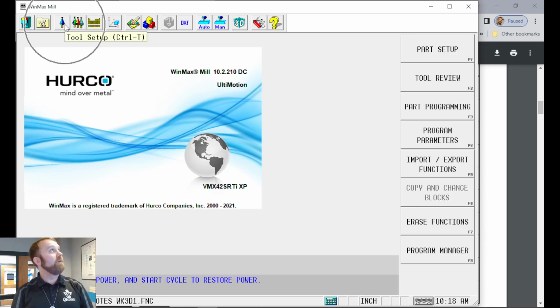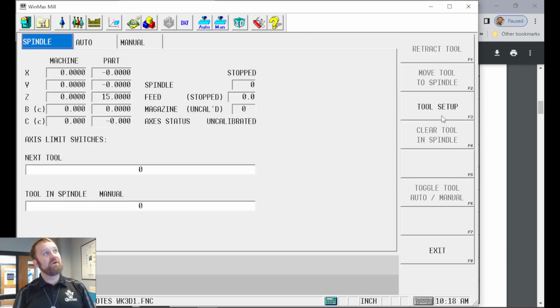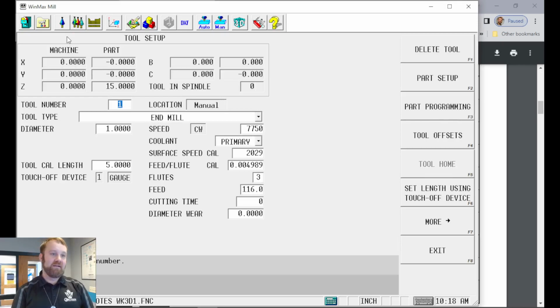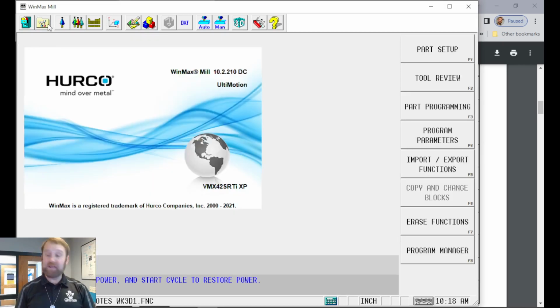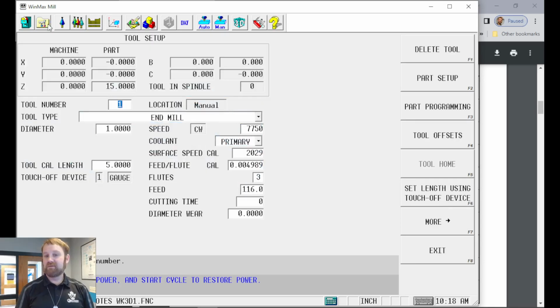Let's go to the tool library button. It's right here, tool setup. So you can go here. There's about 6 different ways you can go over here. You can hit the manual tab and go to tool management and go to tool setup. But I typically, when I want to get there, I usually do the hotkey. I hit Control T. Even out there, when I want to get to my tool setup, I just hit Control T on the keyboard. Okay, the machines out there all have keyboards that slide out, and I usually have it out when I'm working on the machine. Because no matter where I'm at in the control, if I hit Control T, go to my tool setup. Okay, or you can just click the little tool holder right here.